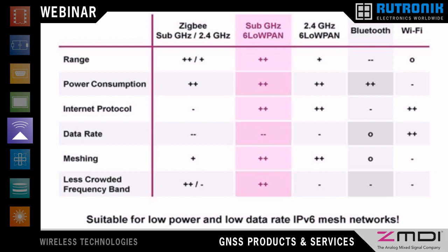Okay, let's continue with our module with the hardware. Our module supports the European frequencies and the North American frequencies. In Europe, we support 4 channels, and the data rate is 20 kilobits per second in the BPSK mode, or 100 kilobits per second in the QPSK mode. The output power is 5 dBm, and the sensitivity is -110.